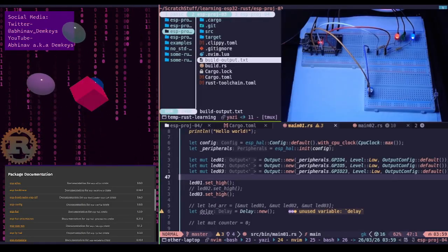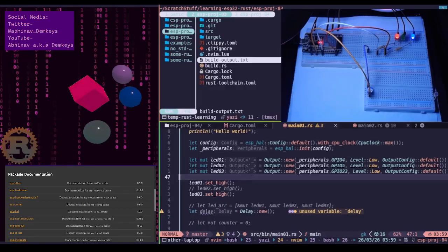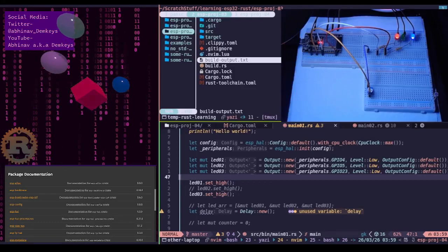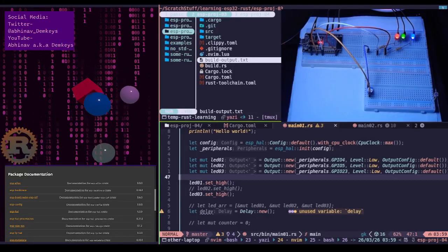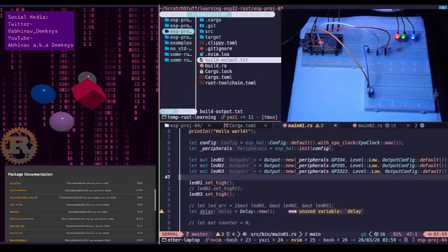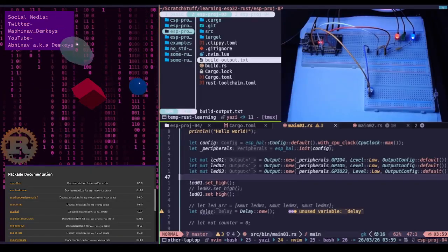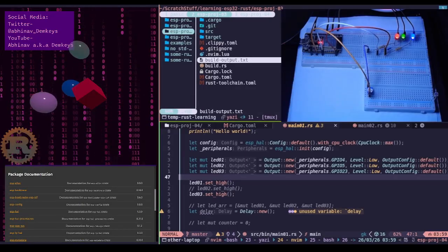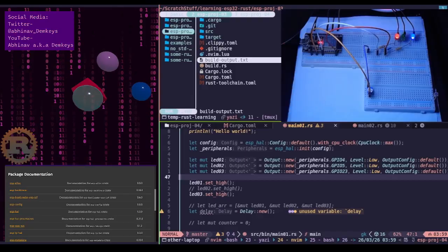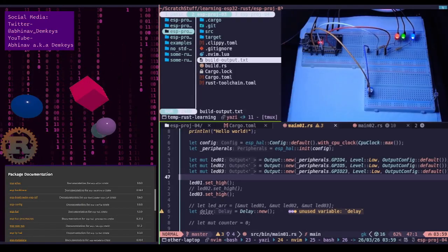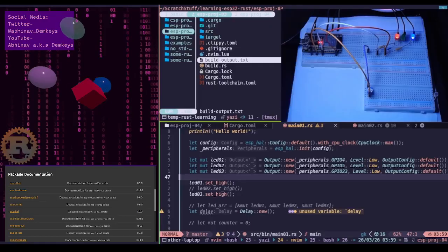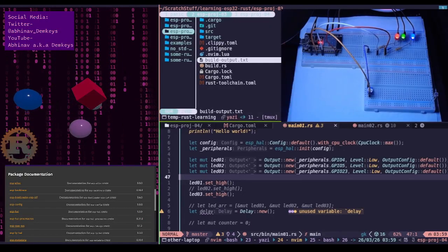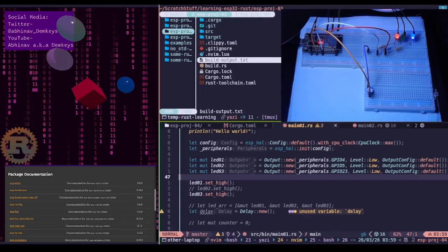I have to set up a circuit with a potentiometer where I connect pin 1 to VCC, pin 2 to ADC, and pin 3 to GND.